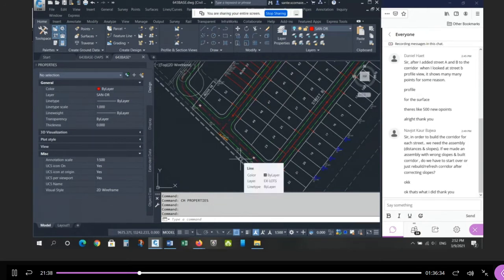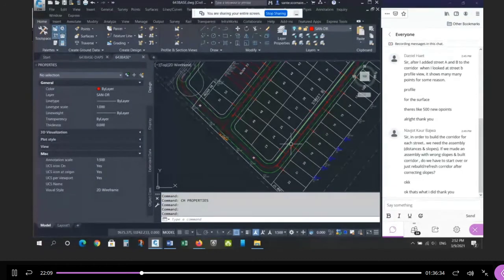If you change the profile and rebuild your corridor, you can update all your points, but only the ones that are going to change are going to get updated. And then you can update just the lot grading that's affected by it, right? So if the front lot corners are the same as before, then your grading should be fine. If they change because the corridor model was updated, then anything born from the front, if the front is different now, you have to redo the grading for it, okay? It's not automatic. Just think about how you built it, right? If you have front lot corners and you do your lot grading and any of the front lot corners change, you have to redo the lot grading in that part of the site.